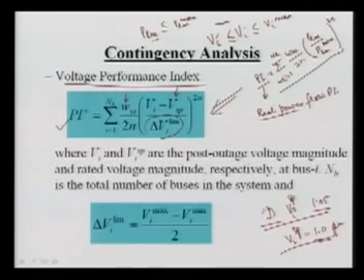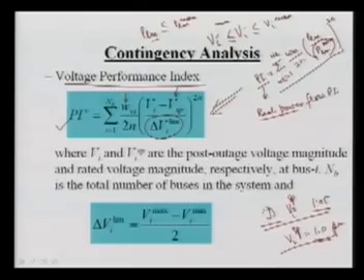Another value here is to make it the range of the limiting value. Here, again, it was also a range. Range means it was P max minus 0, because from 0 to P max it can go, of course, in any direction. So here this value was P max, and here we are taking the Vi limit. This Vi limit is defined as the Vi max, the maximum value at the ith bus, minus the minimum value at the ith bus, divided by 2. So this value is kept here, and then we can go for summation for all the buses.